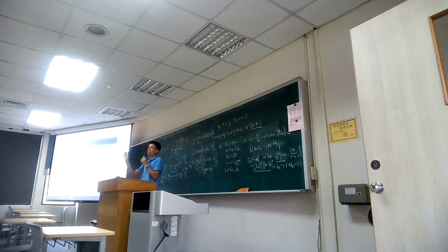If you go back to the metal oxide semiconductor connection in the previous week, we talked about the thickness of the oxide. If you reduce it, you can increase the capacitance. You can increase the current. We want to increase the current because if you have higher current, you charge up and deplete the MOSFET channel quickly, so you get a higher performance of your transistor. That is the power. But then if you further shrink it down, even already to 8 nanometer, what happens? You get leakage. You get some leakage in between the metal and semiconductor through the oxide.